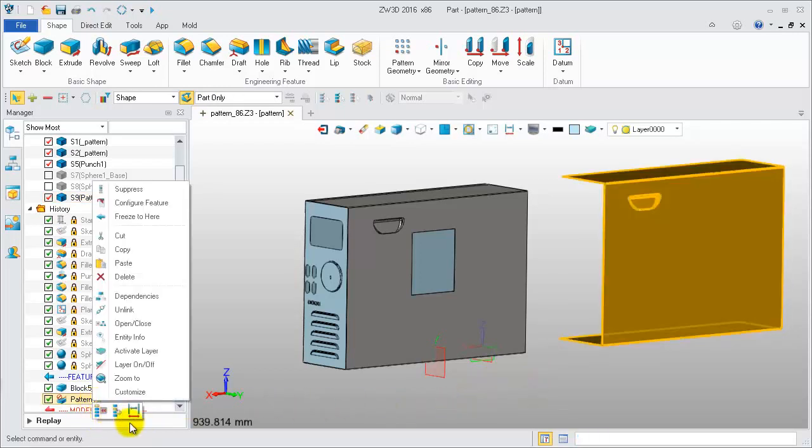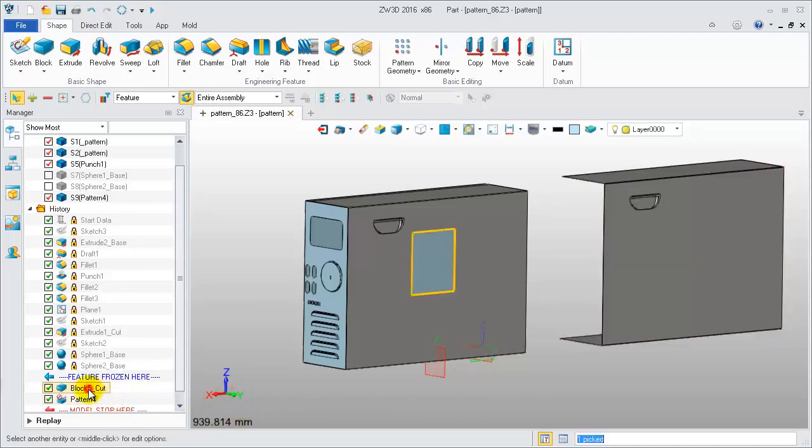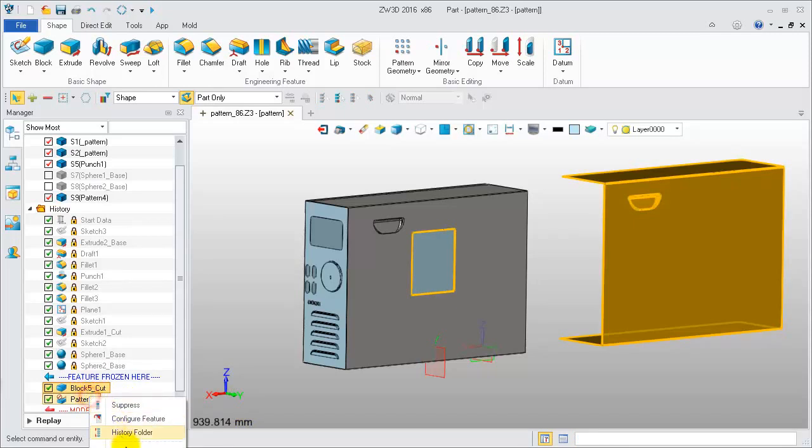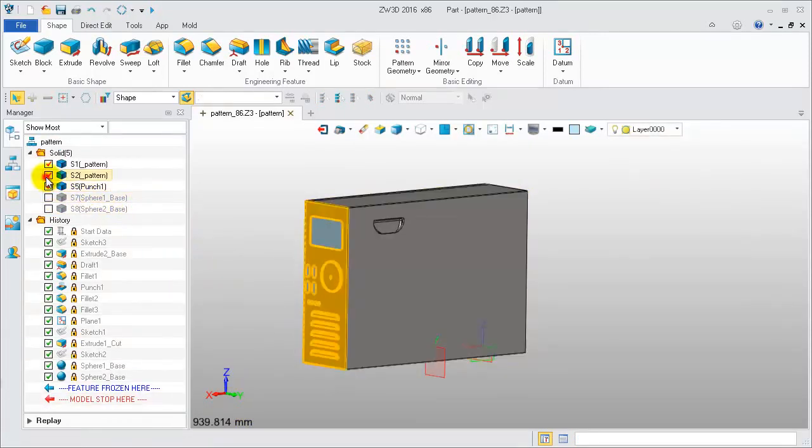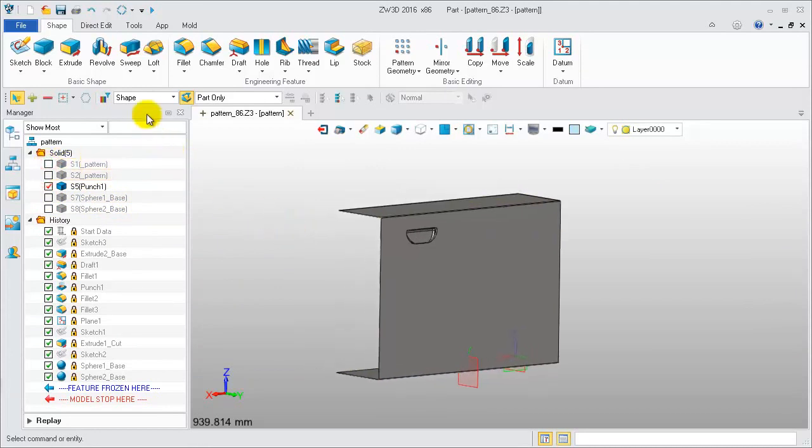If we turn off the associative copy option, the pattern instances will have been created as a strict shape and cannot be redefined. So you should pay attention to which type you want. Let's go on to check the differences between pattern geometry and pattern feature.